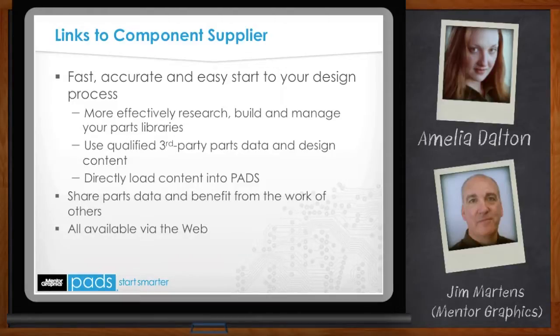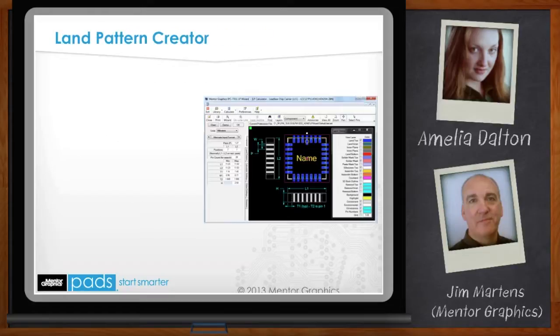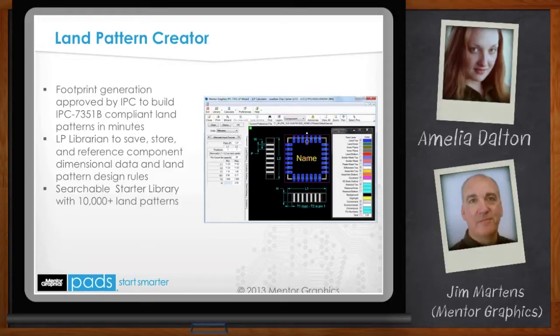So, I still have to build the footprint, right, Jim? Right, so with new parts, you're right, you need a new footprint or new land pattern. So the next thing we're doing in the PADS VX release is adding Land Pattern Creator as core functionality. The Land Pattern Wizard, renamed to Land Pattern Creator now, has been available for additional costs with PADS for several years now. With PADS VX, it is now included with each and every PADS layout bundle or suite. This tool allows you to easily and quickly build land patterns or PADS decals parametrically to IPC standards. We have customers who report they speed up part creation by up to 89% over manual part editing.